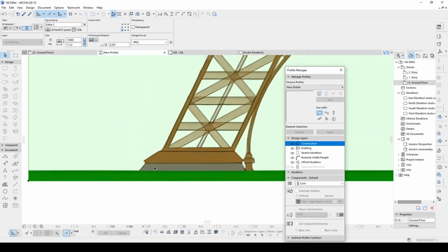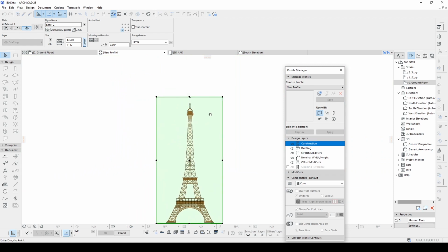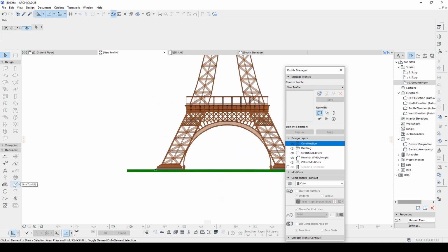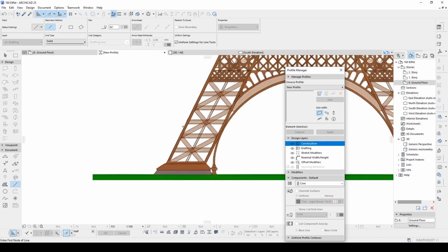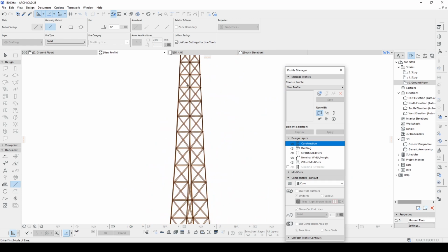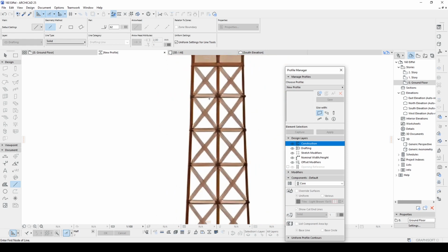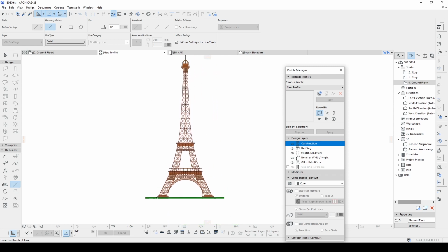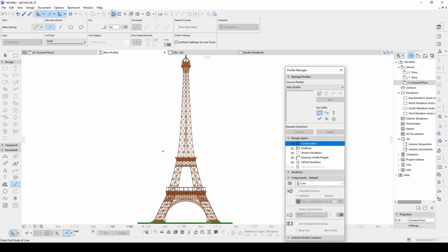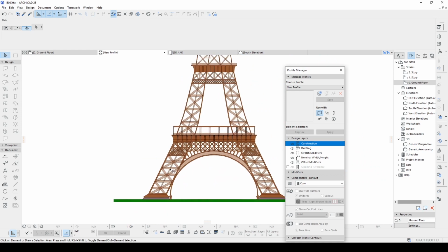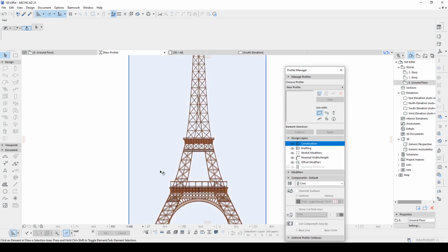At first, I'm going to align this corner, this foot of the tower, to the center point of the profile. And once we have that, we are going to start using lines and also the fill tool. We have two options here. First one is completely drafting the whole tower with sketch and with these inner segments. Then we extrude the shape and then we subtract the profile from this angle. This is the first way. The second way is we only model the shell with this thickness, and we can make a profile with it and then extrude the side segments to get the shape. I prefer the second one, so let's do that.